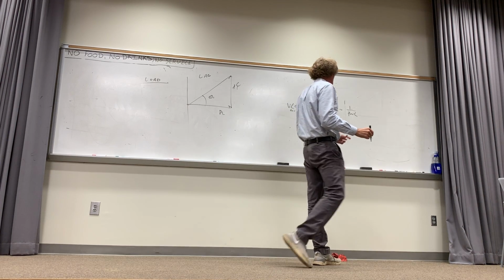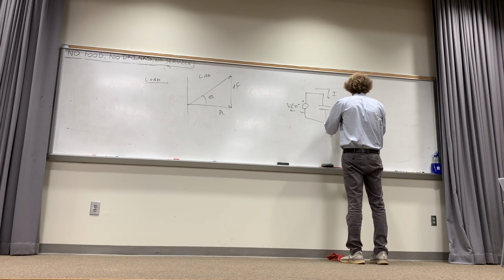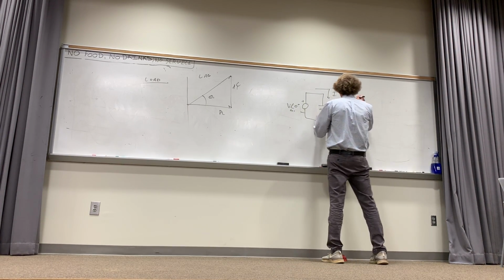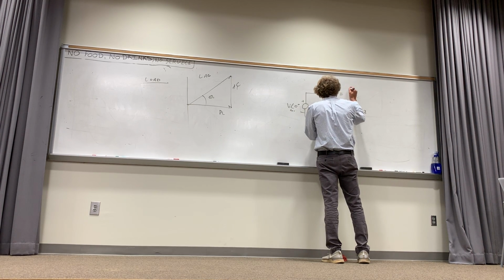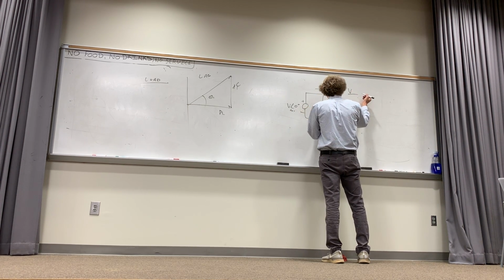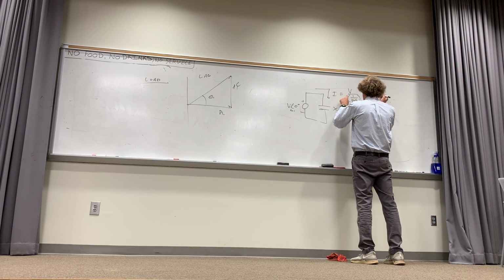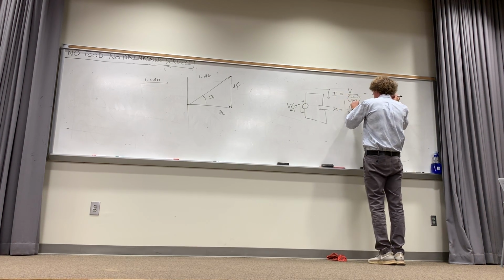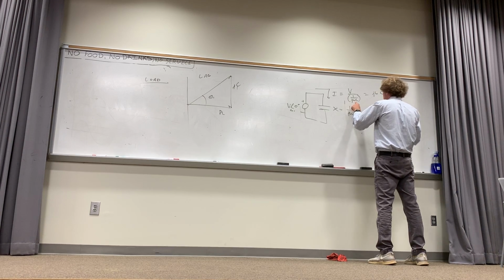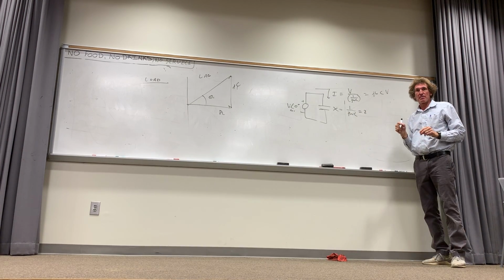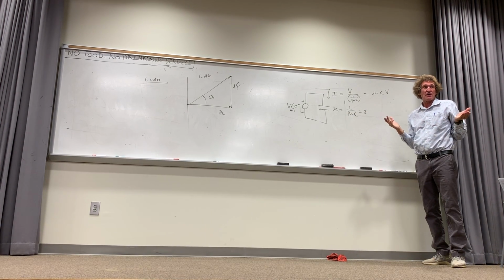It's common. So if that's the reactance, or you can call it the impedance, I can say that I itself would be V, which is at 0 degrees, so I'm not even going to put it, divided by 1 over j omega C. Or really, the current is equal to j omega C times V. Everybody agree with that? Right, I just found the current for a given voltage, agreed?